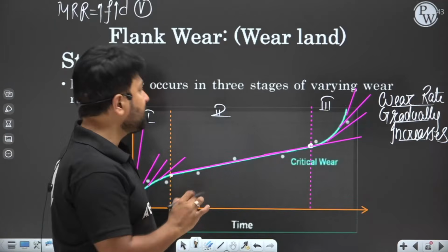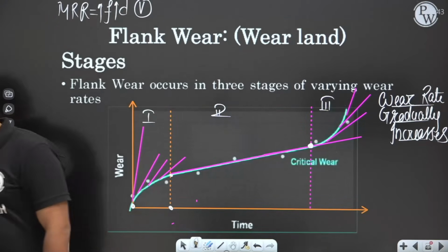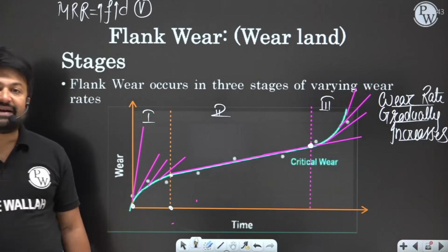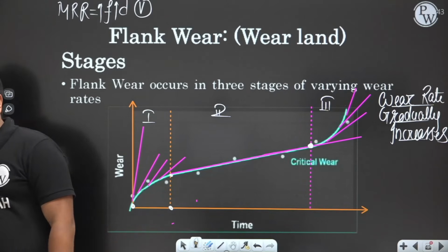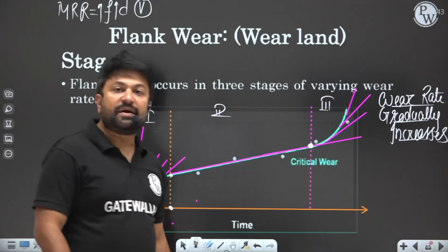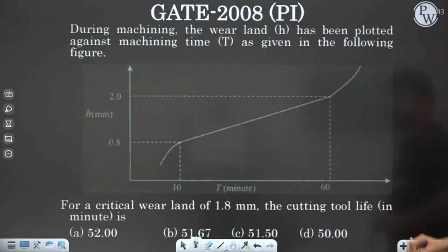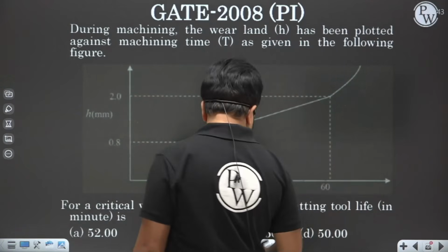So before entering into the tertiary region, it is highly recommended to regrind the tool or to change the tool, right? To change the tool. So I hope the point is crystal clear. Now let's move to the next slide. That is a question, my dear.